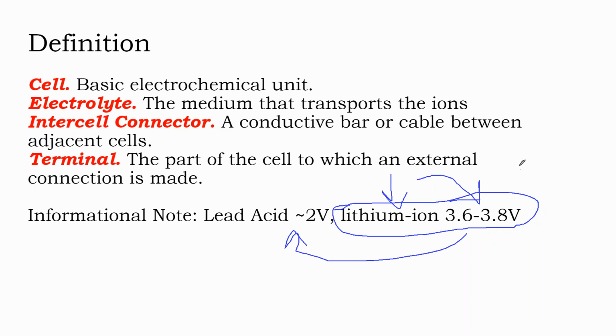The problem with lithium ion is, just like with lead acid, you can charge it too quickly, but more importantly, with a sealed battery, you can't exceed the maximum voltage of that battery. Otherwise, the sealed battery can't contain the pressure. With an unsealed battery, that gas that's being created bubbles out the top, and you can smell it. And you're not supposed to smell it. You're supposed to be evacuating it out of the room with an exhaust fan.